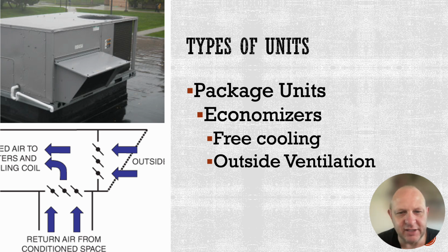It is known as an economizer package. A lot of rooftop units come with economizers, and with the economizer, we are actually cutting the cost of running the refrigeration process by using free cooling from the outdoors.